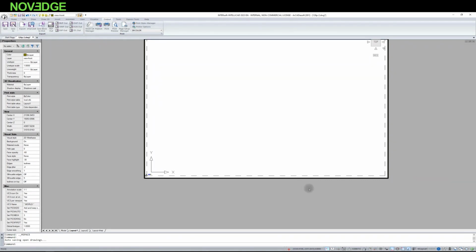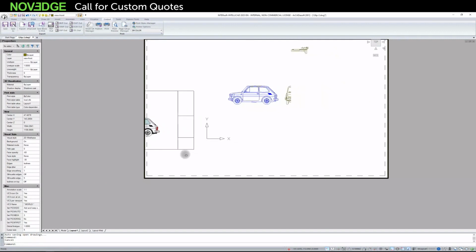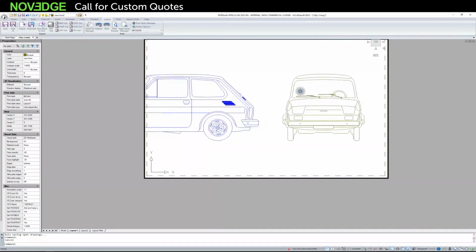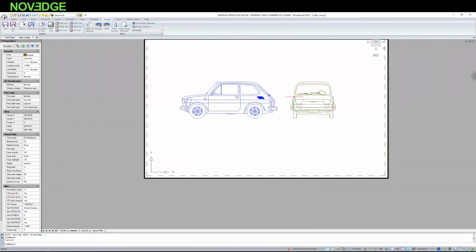So if I click on this place on the right once, please note here, I've changed it, and now I'm in the model. Model:\layout. This viewport becomes bold for me now. And now please notice when I move the zoom, that is the mouse wheel, then I move the model, which is what is in my project, not what is my sheet. And now I can set it up.